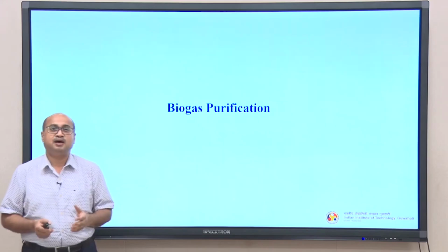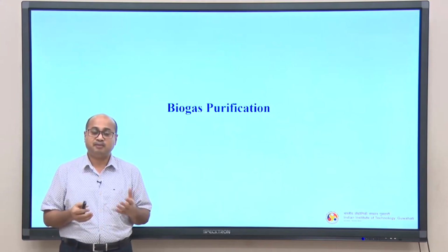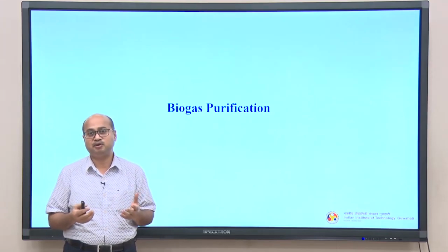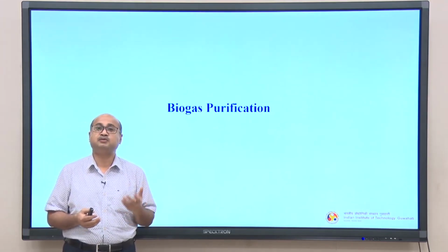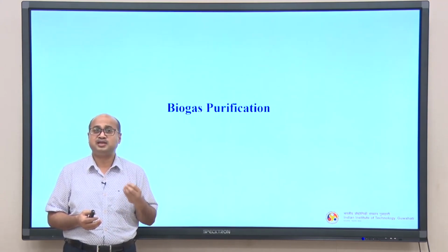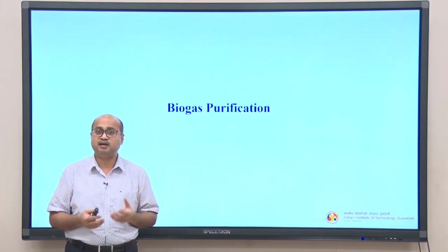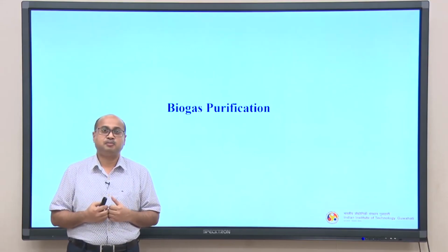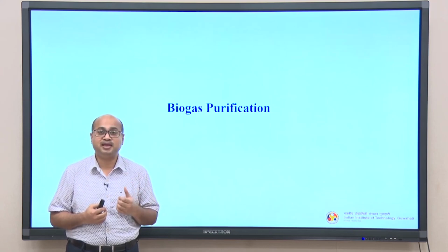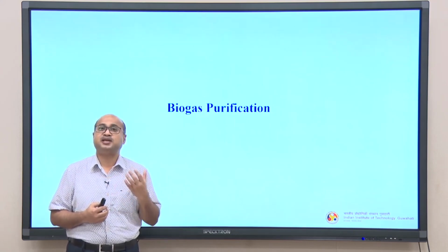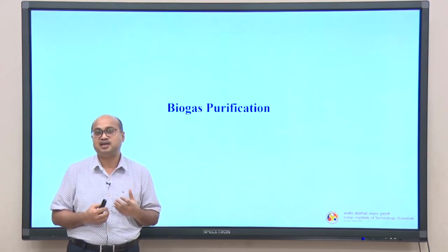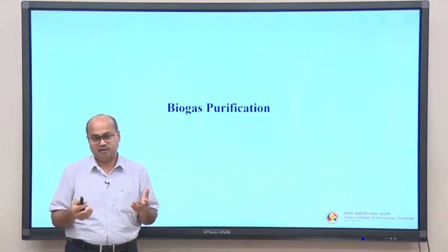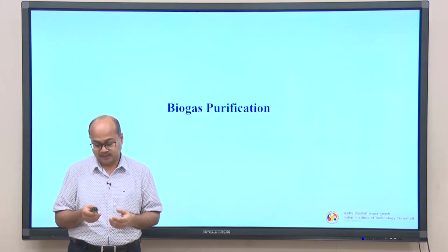So, now we will talk about biogas purification. As I told you in the beginning of the class, biogas consists of many different types of components, starting from the major component methane to carbon dioxide, carbon monoxide, nitrogen, hydrogen, hydrogen sulfide and other compounds. Now, you need to purify them for a particular application. Suppose I am talking about preparing biomethane, then I have to scrub out all the carbon dioxide and everything else, so that I have at least 98% enriched biogas. Then I can call it biomethane, which can be directly used in vehicles.